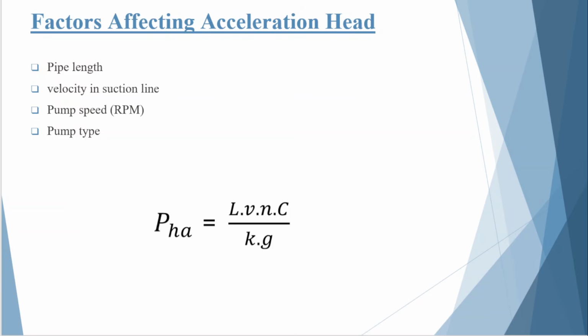The second factor is fluid velocity. Higher liquid velocity means greater momentum. As velocity increases, a larger pressure difference is required to accelerate or decelerate the liquid. Therefore, acceleration head also increases. The third factor is pump speed, or RPM. This is one of the most significant parameters.